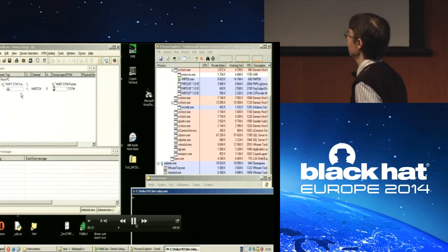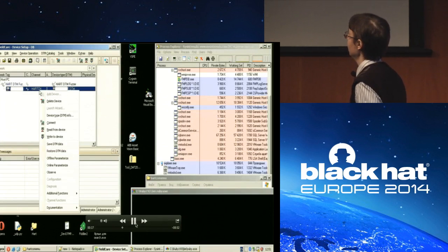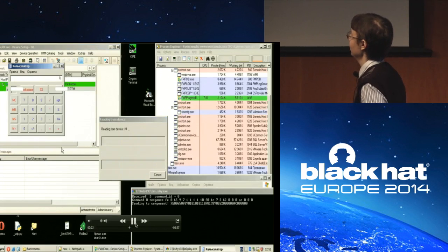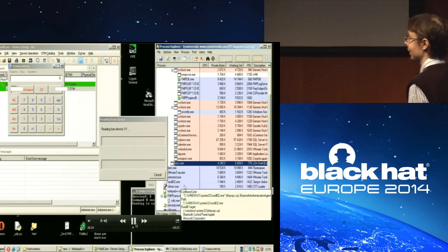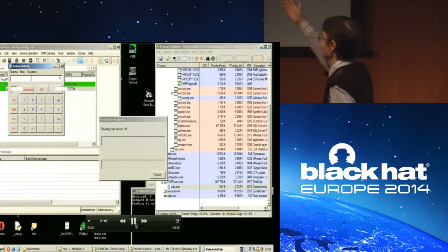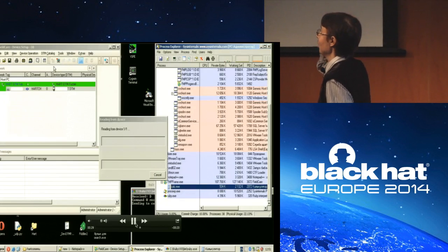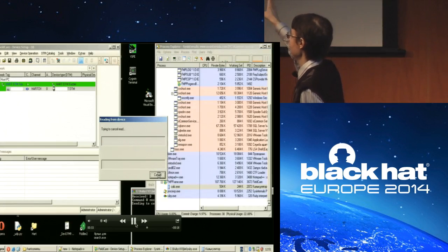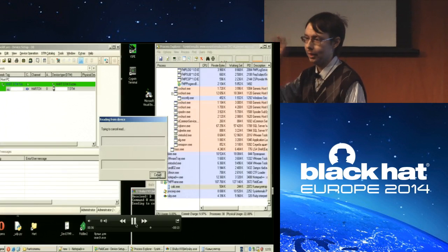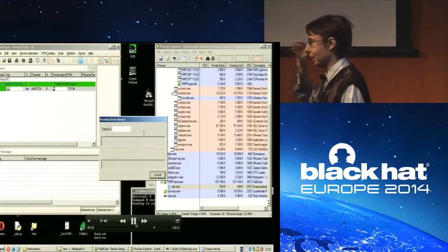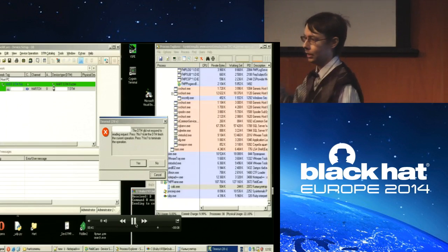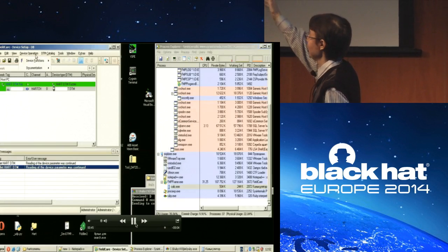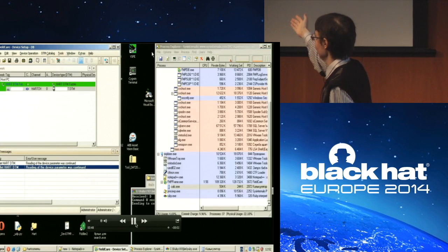And just read data from device. It will be really fast. And here it is, the calculator. As you can see, it runs through the FieldCare frame. Moreover, we just now cancel the transaction, the timeout will pass, and FieldCare will stay alive. So we could remotely execute code in the context of FieldCare, and the field engineer won't notice anything. FieldCare just continues normal work, and the calculator is running.